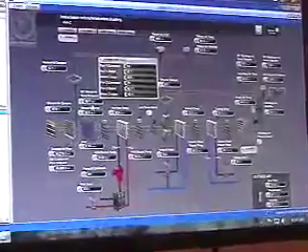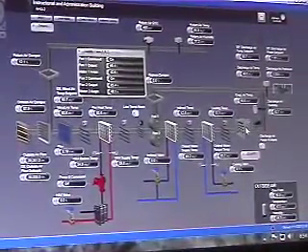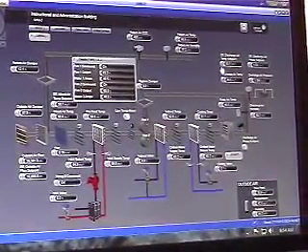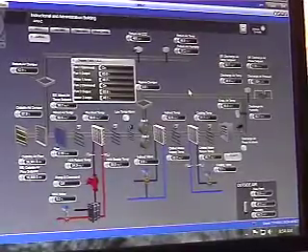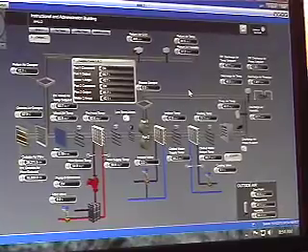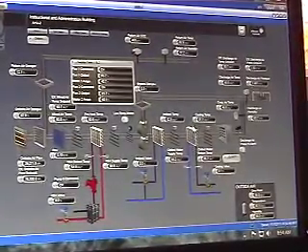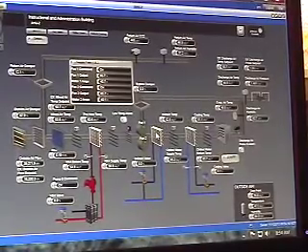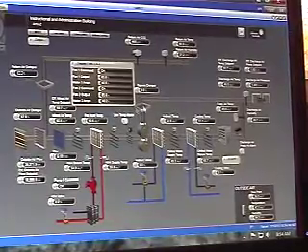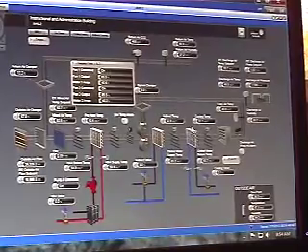so from here, here's your mixed air temperature set point. Evap media has a 2 degrees above there. So if we're 2 degrees above our set point, and you'll see where it'll all change right here, we then switch to the next state, which is state 4, your indirect coil. Your indirect coil will then modulate up and down to maintain temperature. Your evap media in that mode actually stays 100% open, fully on. This damper would be closed, and we're using the indirect coil now to maintain temperature up and down.